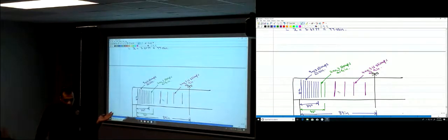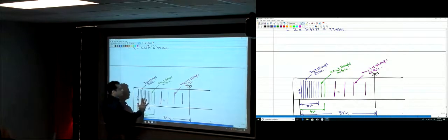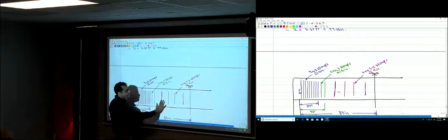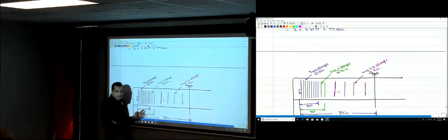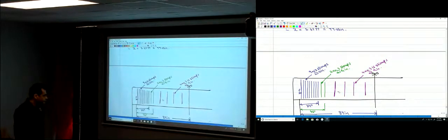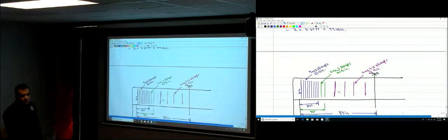It's up to you. Because let's say you provided 4 inches, and then you didn't provide this 6 inches spacing, you just provided the 9 inches right away. That's still a good design, okay? But you're just going to have to provide the 4 inches spacing for a longer distance. So it's just the choice of the designer himself, okay?